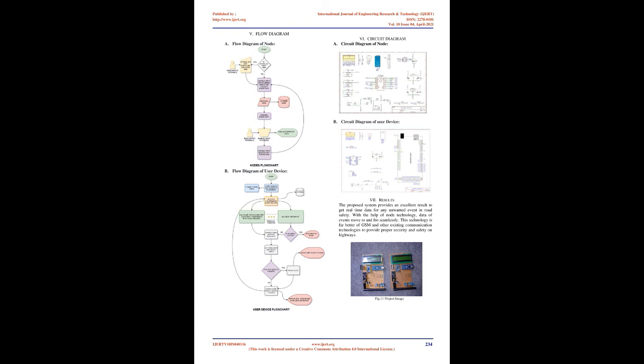F. nRF24L01 Plus is a single-chip radio transceiver for the worldwide 2.4 to 2.5 GHz ISM band. The radio transmitter and receiver include a frequency generator, enhanced shock burst mode controller, power amplifier, oscillator, modulator and demodulator. You can select the output power channel and protocol by setting through the SPI port.